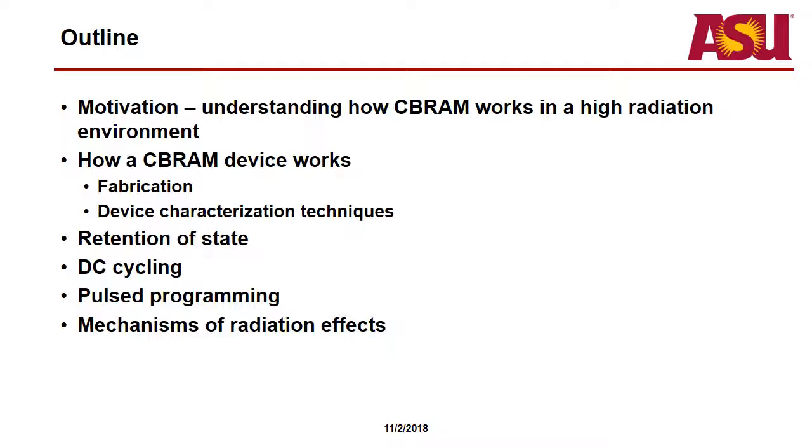But I'm also going to cover how CB-RAM devices work, how I make them, how I test them, and then get into the radiation effects during retention of state tests, DC cycling, and pulsed programming, more oriented towards neuromorphic pulse tests. And then lastly, I'll discuss how the effects that we observe during those electrical tests correspond to material changes that we see, and the mechanisms that are causing those observable radiation effects.